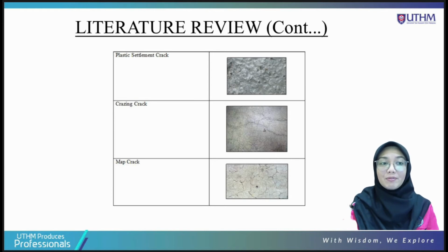It is common for the crack to form along the length of the reinforcement bar. Next, the crazing crack. Fine cracks are the only ones of this class. In buildings, it is a minor cosmetic problem. It is not possible to notice the cracks. However, if the concrete is wet and dry, we can see the crack patterns.